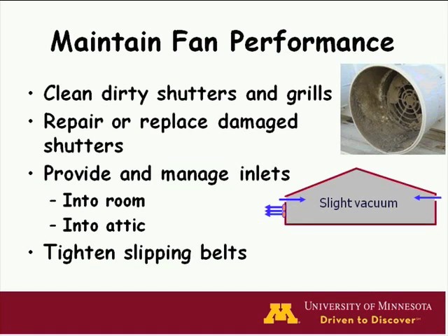To save energy, it's important to maintain our fans, and some of the things to do there are to clean dirty shutters and grills, and replace and repair damaged shutters. If you are going to be lubricating shutters, it is important to use graphite rather than an oil, because oil tends to collect dirt, and that reduces the operation of the shutters again.